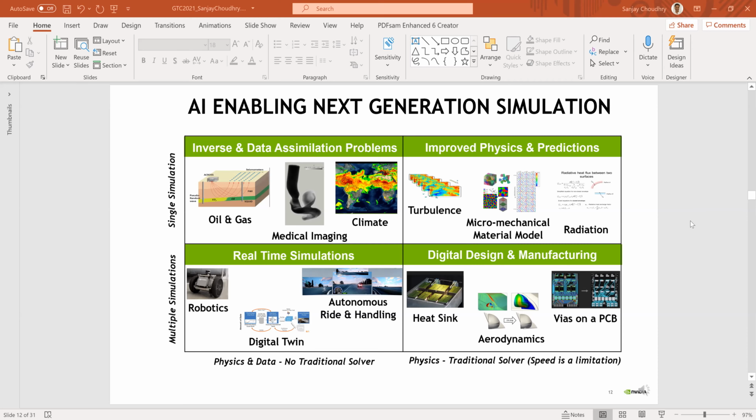Basically, for the constant velocity model, you can see that the comparison with a finite difference code, Devito, that exists on the GitHub for small times is excellent, and it continues to be that way. But there is slight reflection shown by the finite difference code, which should not exist because the boundary conditions are not reflective.